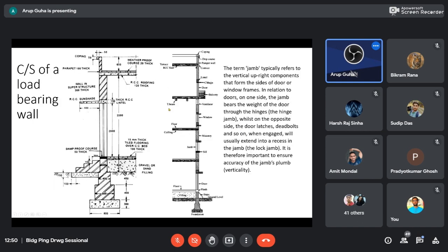Okay. Now here, a bit more detail. Foundation. Once again, I will not pay much importance to the dimensions that I have given, but here, this is a plain cement concrete slab on which you are building, and this is actually tapering stepwise. What happens? The entire load is coming through this wall, and soil cannot take that much load.